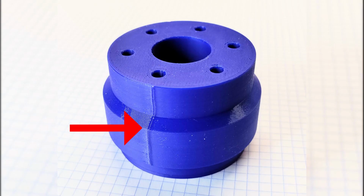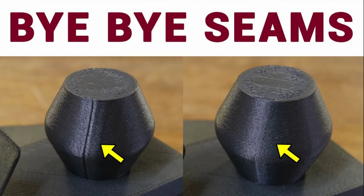Even seams are a scheduling problem. Where the slicer chooses to start and stop extrusion on each layer determines where seams appear. You can tell the slicer to hide seams on corners, align them, randomize them, or place them on the back. Each option is a different strategy for dealing with an unavoidable artifact. The seam exists because extrusion has to start and stop somewhere. The slicer's job is to make that transition as invisible as possible, but it can't eliminate it entirely.